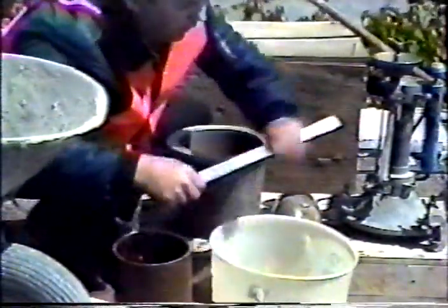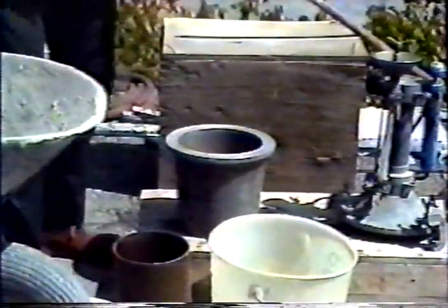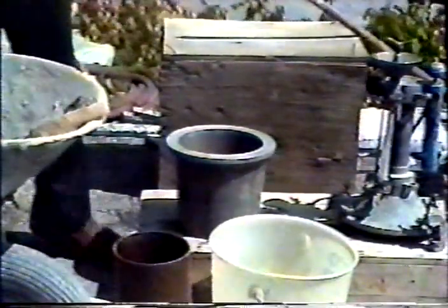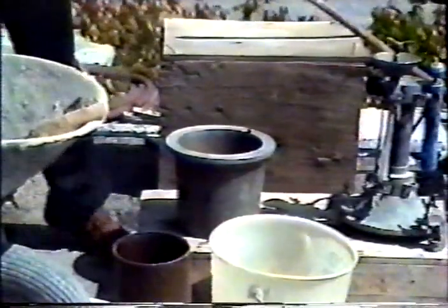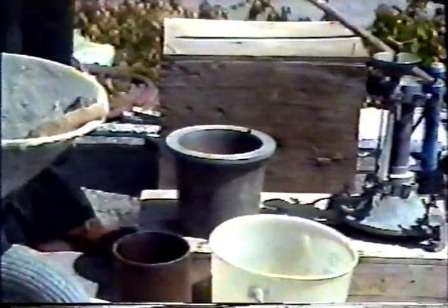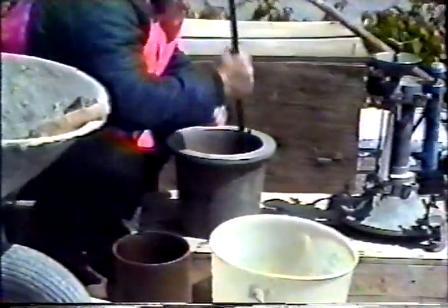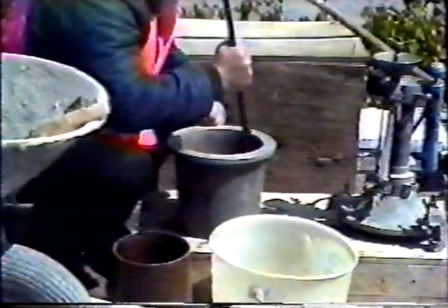As with the slump test, all the equipment should be clean and in good condition. It should be assembled near the concrete sample. The test is begun by filling the measuring bowl with concrete in either 2 or 3 equal layers and consolidating each one. The number of layers depends on whether the consolidating is done by rodding or vibrating. And the method of consolidation depends on the result of the slump test just performed.